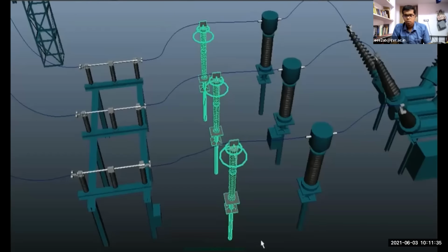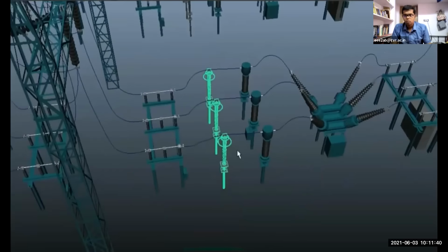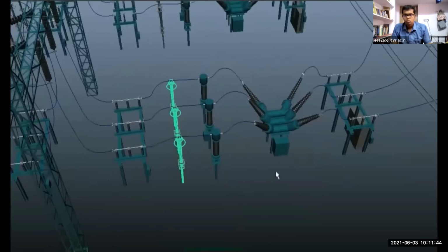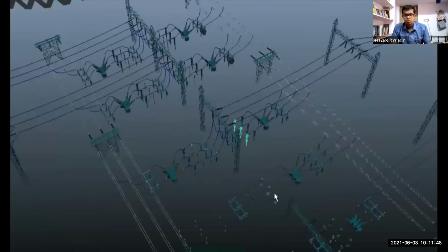The current and voltage transformers installed at different places in the system not only measure the value of current or voltage in the respective line, but also give input to the relays. They detect any abnormal change in their value and operate the circuit breaker to take preventive action and therefore protect the complete system. So this is about the double bus arrangement which our power plant switchyard generally consists of.